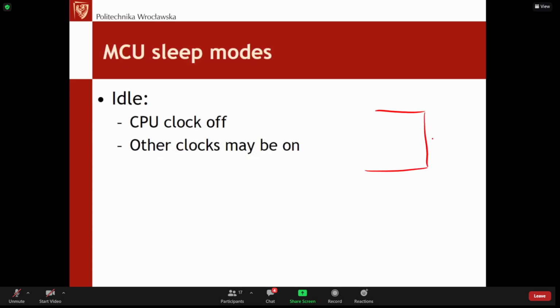Consider that we have a decoupling capacitor. Even if this is a 100 nanofarad capacitor, decoupling gets some power supply input, and then the power supply pin. If we switch off the power supply, then the capacitor will self-discharge after some time because of the parasitic resistance.